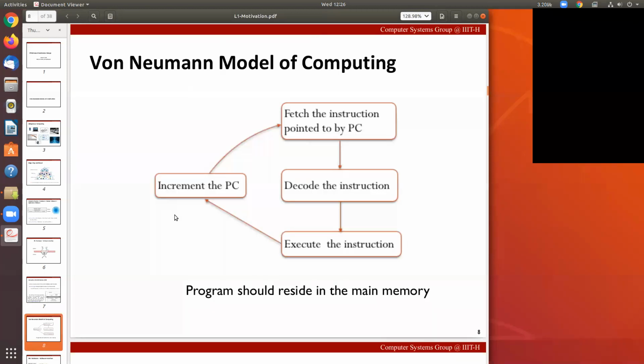And then if you take a little bit of a deep dive into the instruction set architecture, it tells the statics of the system. For example, it says what an add instruction is. If there is an instruction like add R1, R2, R3, the semantics of this instruction is that you add the contents of registers R2 and R3 and store the result in R1. So the instruction set architecture defines all the instructions that are present in the ISA and the semantics of those instructions.